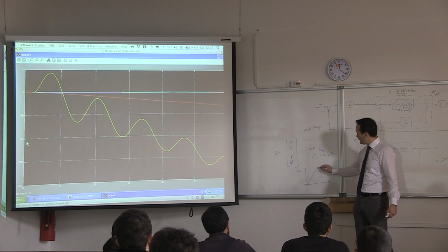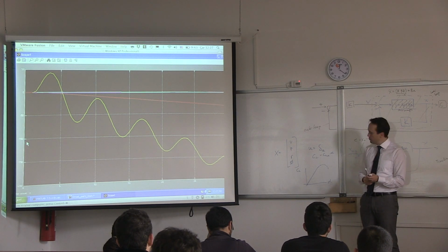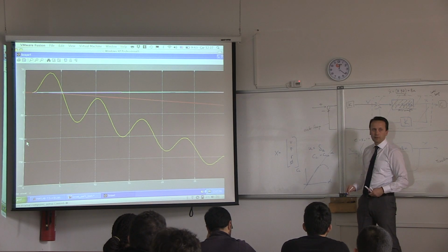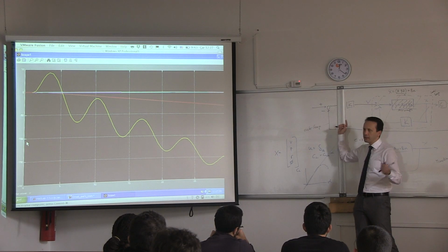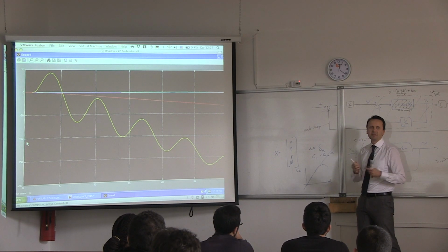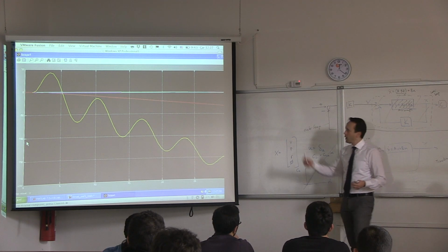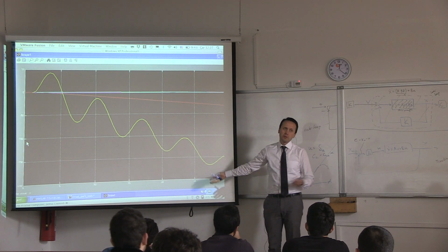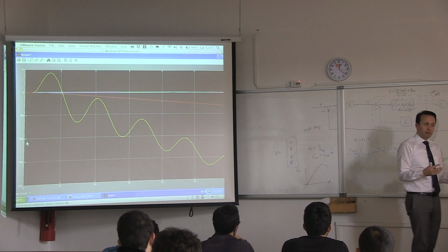In real life, the nonlinear model does this. This is nonlinear. Okay? But a linear model means this. It goes to infinity. Which means if you have alpha of 1 million, you will get a CL of maybe 10 million. It's physically not possible. But because it's a linear model, you will see that. So I'm using a linear model here, and you get all these large numbers, which might not mean anything in real life, but we have to be aware of this.